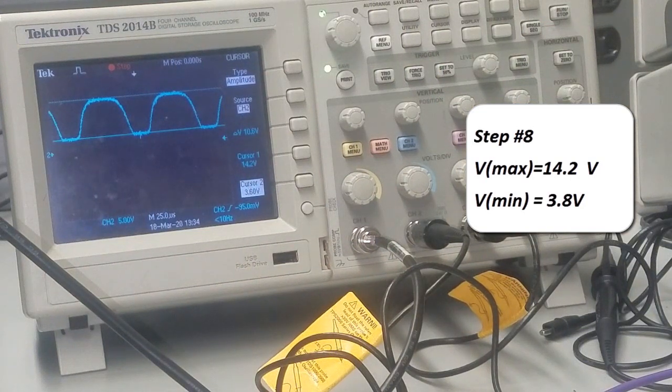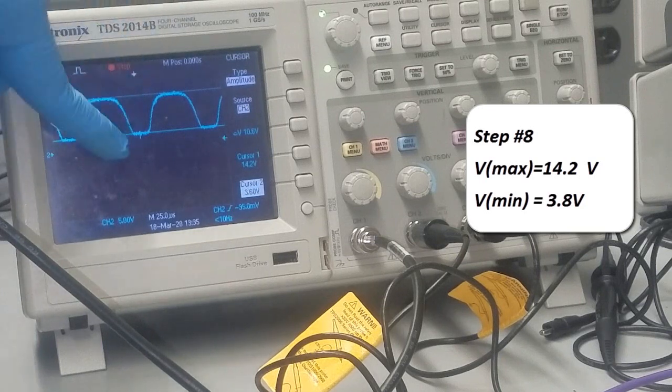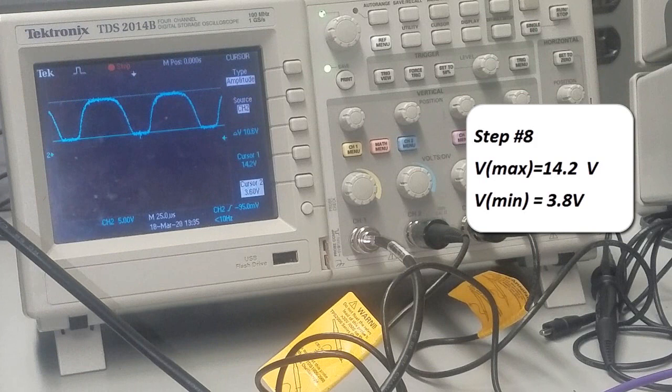So usually the transistor will clip from the bottom when it enters the triode region, and it will clip from the top when the voltage is very close to VCC, because when the current is very small, the transistor is not amplifying anymore. So it's clipping from the top and from the bottom: at the bottom it enters the triode region, and at the top the current is too small. gm is very small, so it doesn't give you a very good amplification, so it clips from the top and the bottom. This is the voltage at the drain.